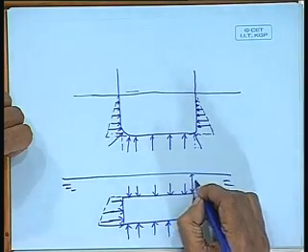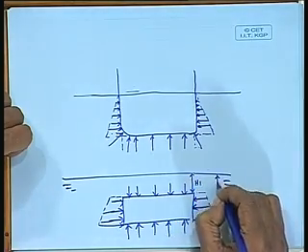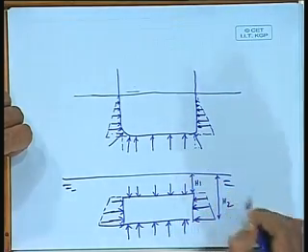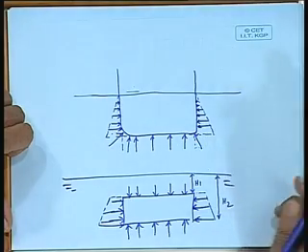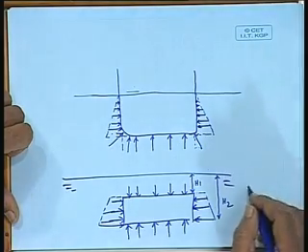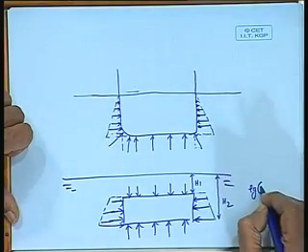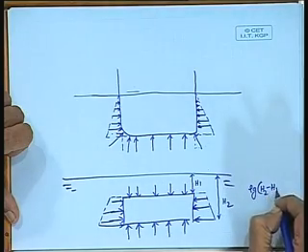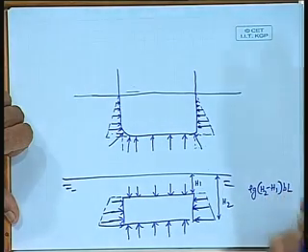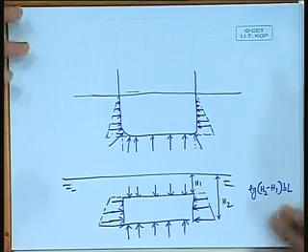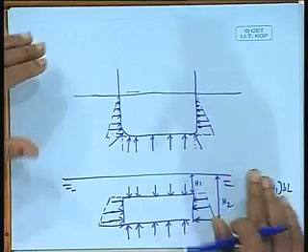You get it? Now, if this is h1 and this height is h2, the force acting on this will be rho g (h2 minus h1) into breadth into length, whatever length you take. And what is this? This is also the total volume. So, the force acting on it is equal to the mass of the total water displaced, an upward force.